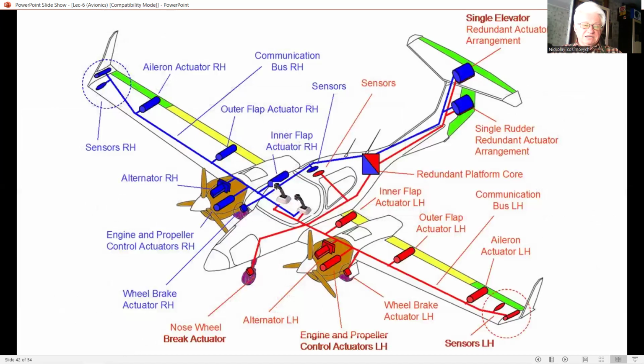If the disconnect threshold is set too low, a sensor can be deemed to have failed and be disconnected when it is merely at the edge of its specification tolerance. Otherwise known as a nuisance disconnection. Conversely, if set too high, when a real failure does occur, the magnitude of the transient on disconnecting the failed sensor can be unacceptably large.